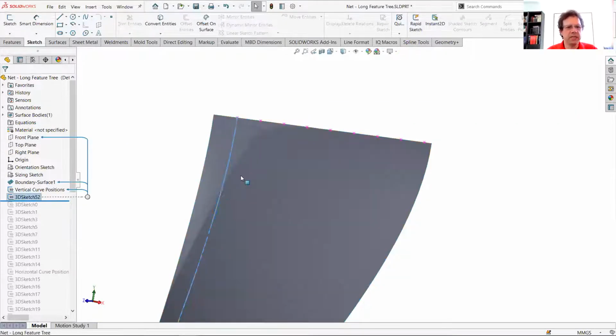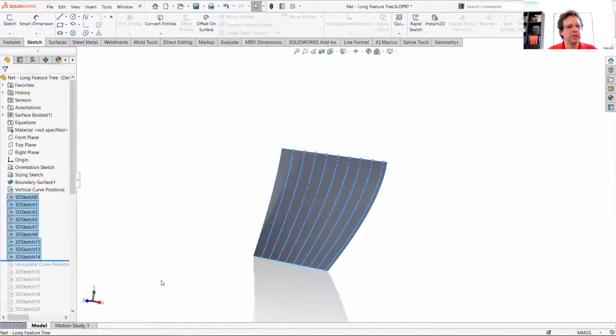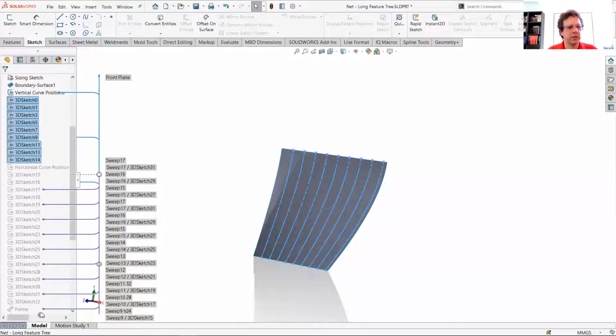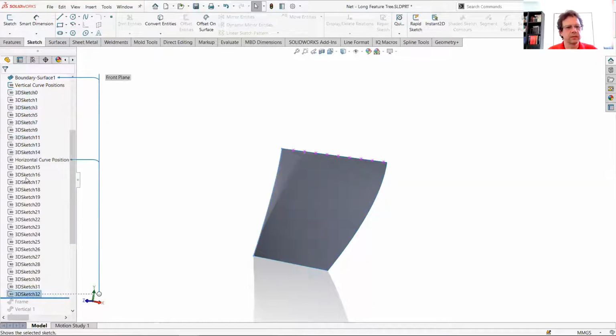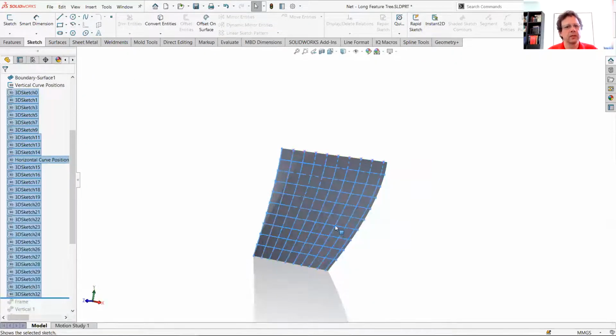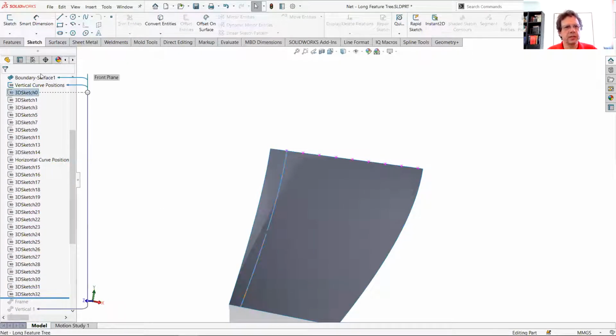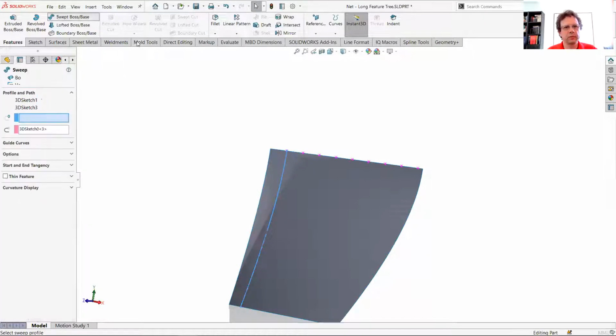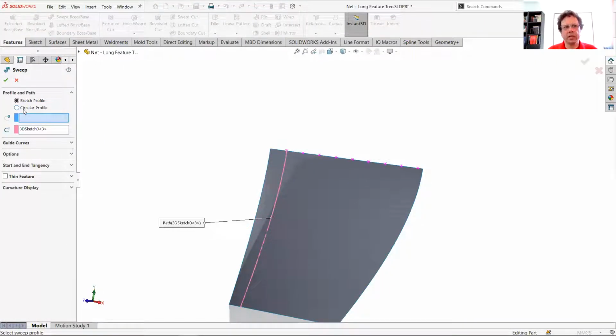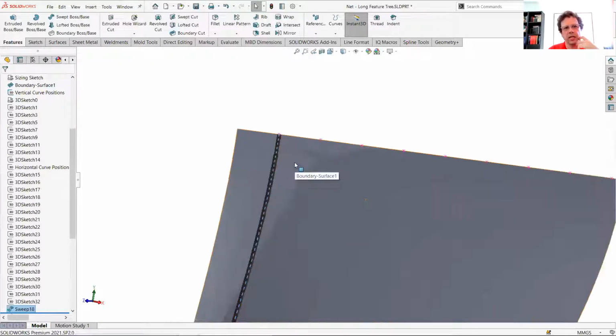And this is pretty much what I did down the road. So allow me to reveal the other sketches that were created this way, right? All these ones in this direction. And in the horizontal direction, a few others. Right, so all these are the lines. What's next? Well, you take each and every one of these sketches and use it in a sweep. One cool thing about sweeps, I hope you guys know, if you just need a circular profile that is centered on those paths, you can simply specify its diameter, let's say 50 millimeter. So if I click OK, now this is my rope.